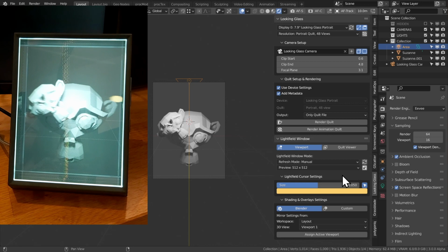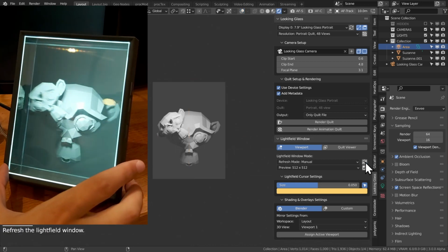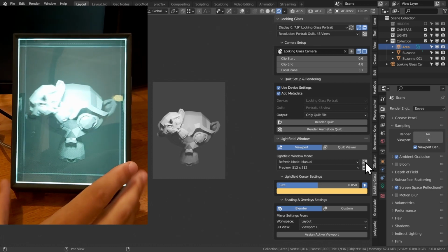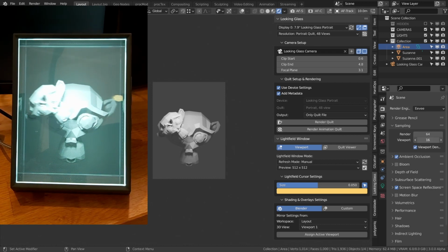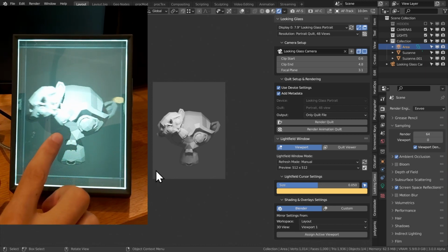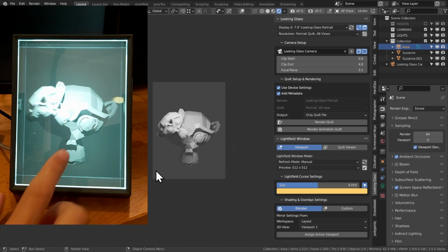If you want to hide your overlays as well, then that's going to just hide any of these. There we go. Any of those extra bits. If it's looking a little bit dark, it might be that your viewport samples are set really low. By default, I would actually have my viewport sampling set to 0, and that basically means that it will just sample infinitely in Blender, but that is a problem for the display. So when that happens, it only does a single pass, and we can see that we end up with these really sharp lines in the shadows.